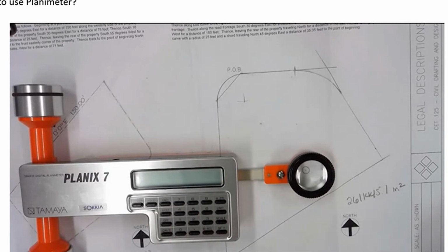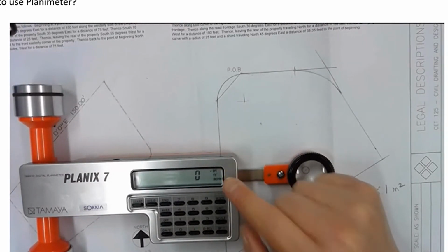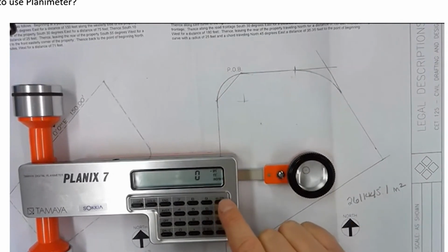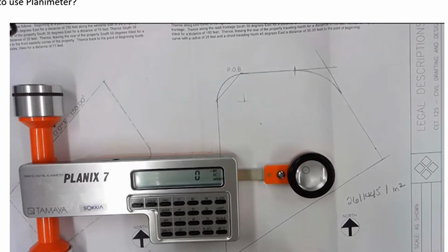So the first thing that you're going to want to do when you use the planimeter is turn it on. You'll see the on button right here, okay? And then you're going to want to check your units. In this case, I'm already in good shape because I'm in inches, feet, and acres, but this button right here that says meters to feet will toggle you between metric and English units. And then you can click the unit button and you'll see the little tick mark moving up and down and you can change between inches, square feet, and acres.